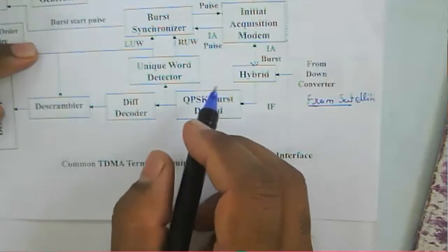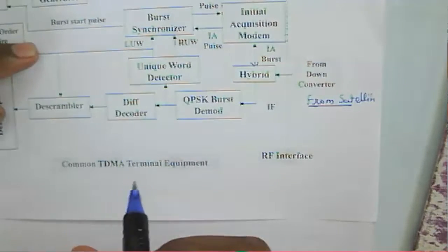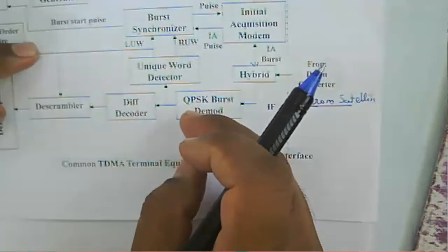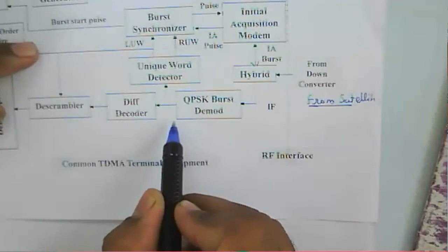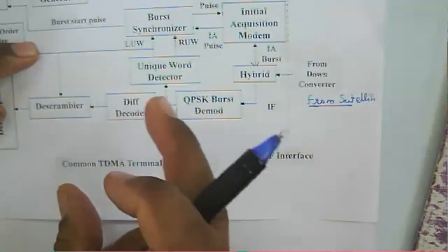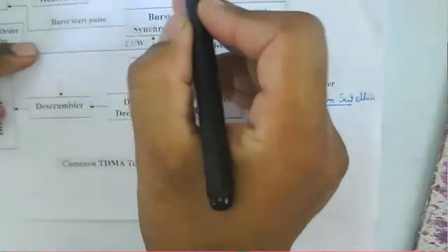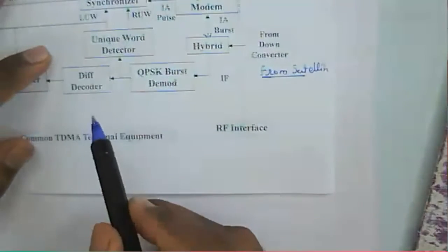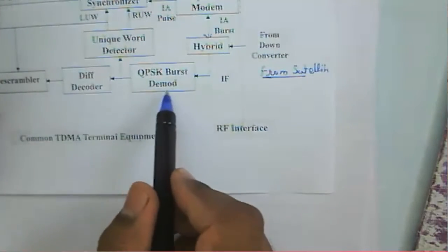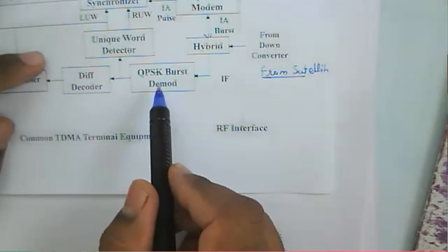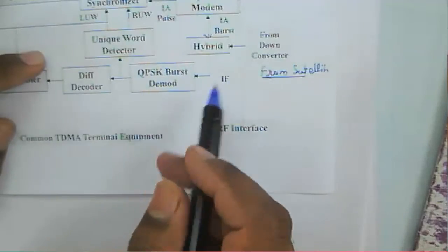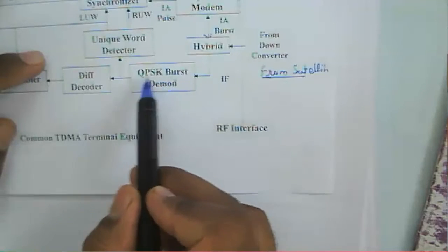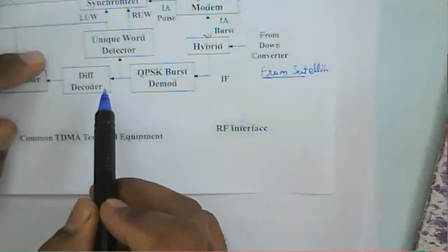Now, the role of this particular QPSK demodulator is to demodulate the data, and the demodulator must recover the carrier completely, as well as the phase there. Because at the transmitting side we have phase and carrier, similarly at the receiving side, the demodulator recovers the complete carrier information from each IF signal, and then that is useful for the recovery of the clock.